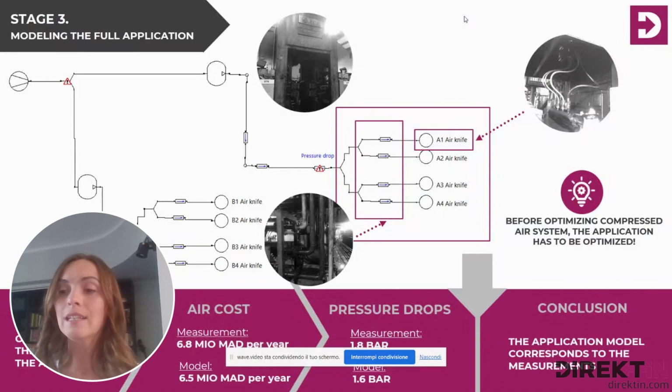So when the machine started to work, the manometer would drop to 3 bars. The outlet of the application is about 2.2 bars, so it's quite low pressure that results in the blowing force of 70 newtons, and the consumption there was around 366 cubic meter per hour.